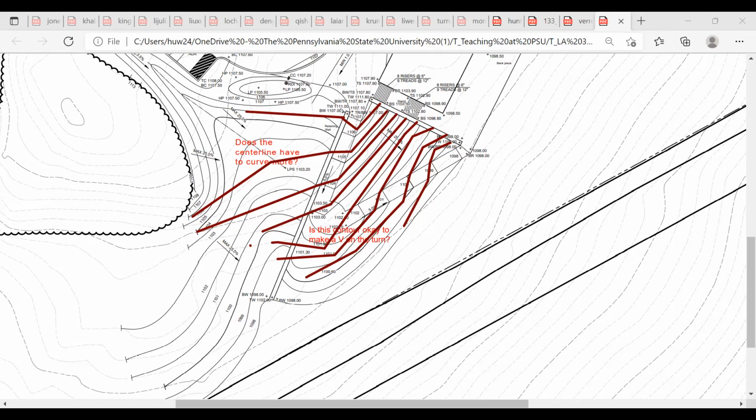But that ultimately will need you to calculate. If you're able to keep slope within limits, you can move everything up like that. That makes sense? So that you stay relatively close to where your original calculated contours are.